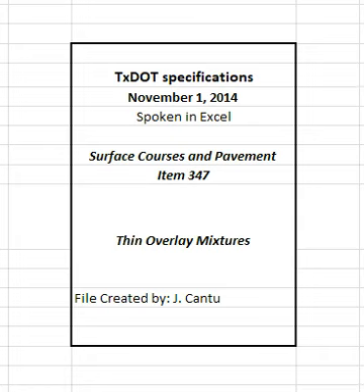4.9.2 Production Acceptance. 4.9.2.1 Production Lot. A production lot consists of 4 equal sublots. The default quantity for Lot 1 is 500 tons, however, when requested by the contractor, the engineer may increase the quantity for Lot 1 to no more than 2,000 tons.